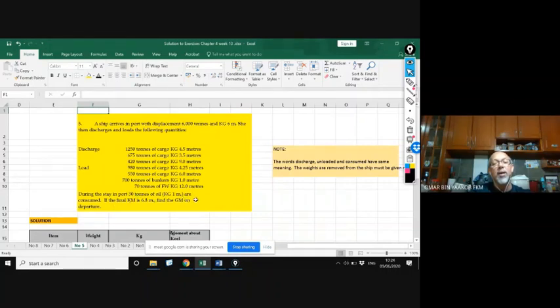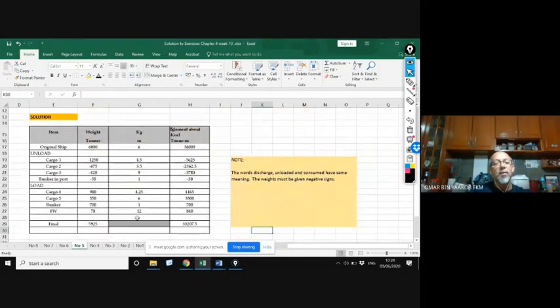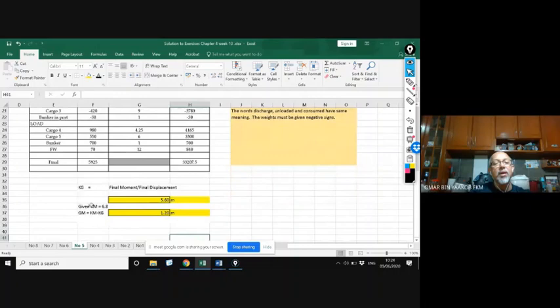So 30 tons of bunker. Bunker is the same as oil, the oil being burned. Right, so there we have the total moment, and again find the kg. Given km is 6.8, gm is 1.2.